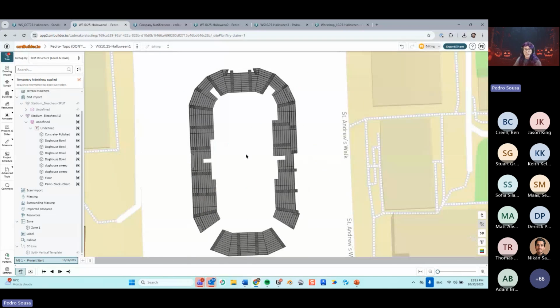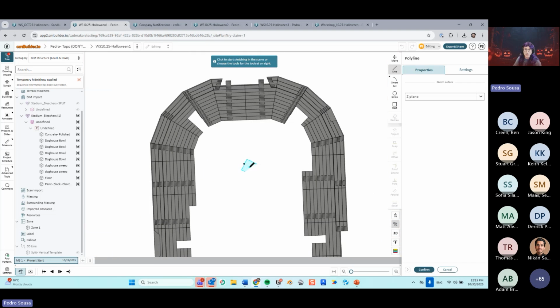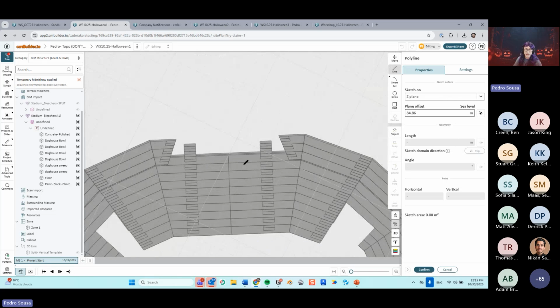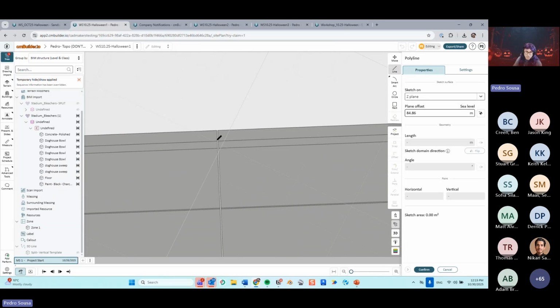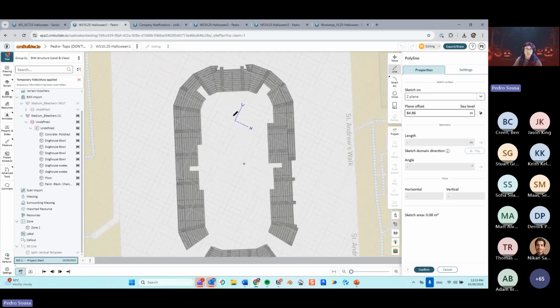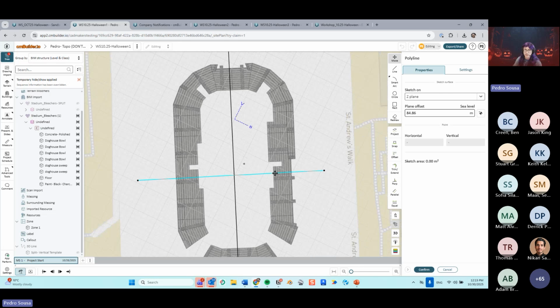And I really suggest that you draw your split lines first as a 3D line tool, because it's easier for you to go back and change that without going into the split geometry tool and make those changes, right? So if I were to do this again from scratch, I would just create my line over here in the beginning. I'm gonna do it just for a few, okay? And since the pour break over here is so thin, I can basically just do one big line here first, and then another big line here,